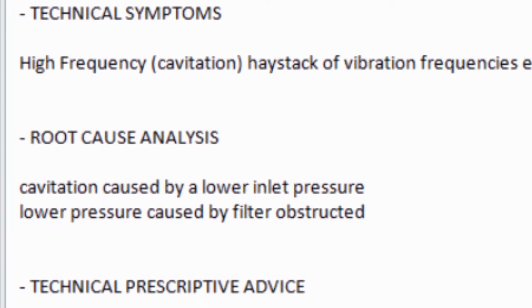Root cause analysis. Thanks to the holistic monitoring of the circuit, by correlating the process and condition data all together, we are able to understand the initial cause that has created the pump cavitation. As described, the cavitation is due to lowering of the incoming pressure. But not only. We are told that this problem is caused by another component outside the pump, the filter.